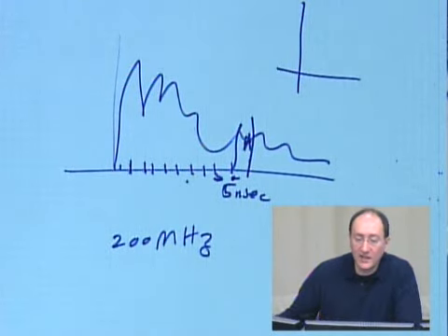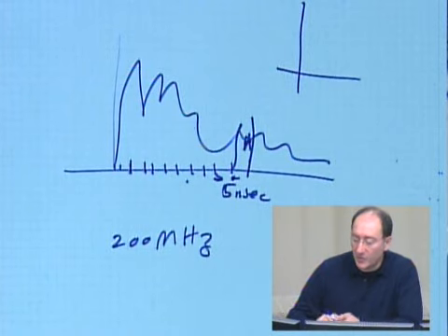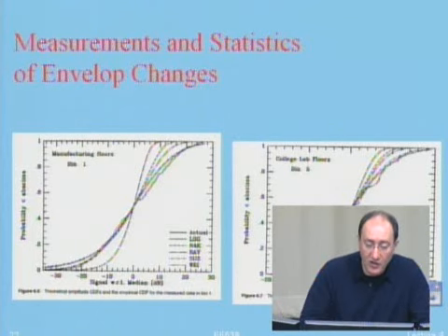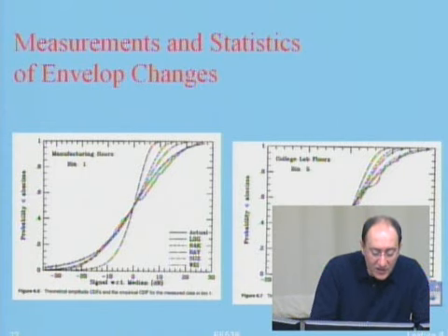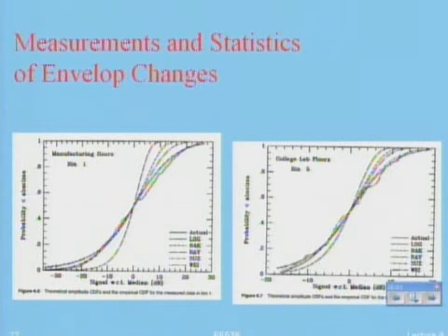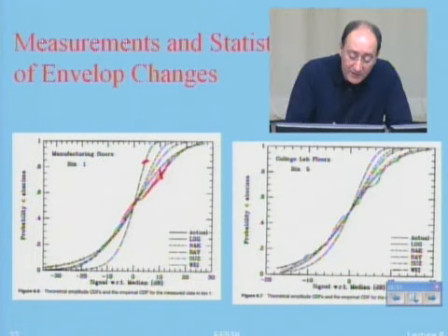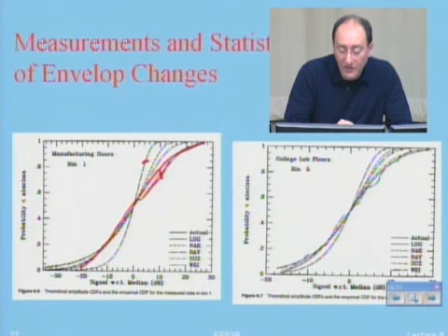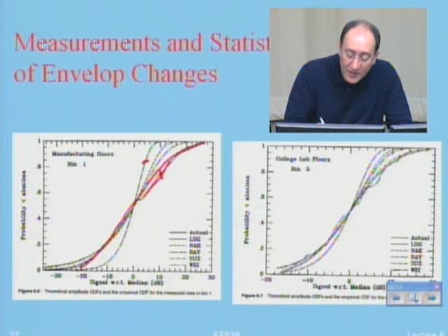And when they do it, to fit with the curves, they come up with things like this. If we come back with the computer, we see that. These are cumulative distribution functions of different distribution functions. This particular one is Rayleigh. This one is the measurement. And then this is log normal. So you can see several: log normal, Nakagami, Rayleigh, Suzuki, and Weibull.